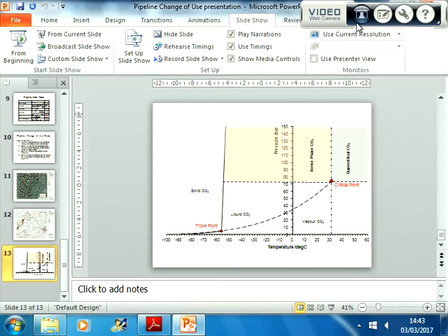So it is like mixed phase? I think if you look up dense phase, it will say that it's got the density of a liquid but the viscosity of a gas. So it's sort of like a funny state. And in reality, dense phase in any fluid is usually the best phase to transport it in. It's the most efficient phase to transport it in.